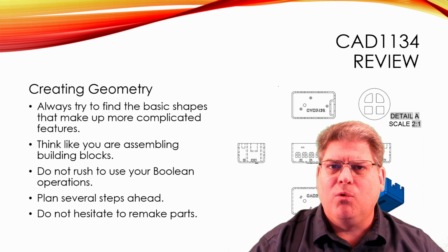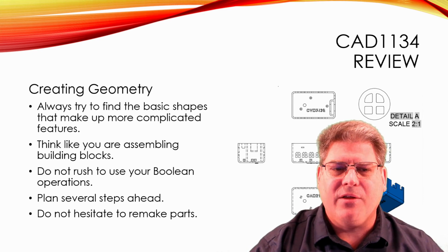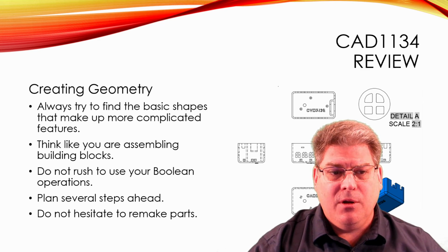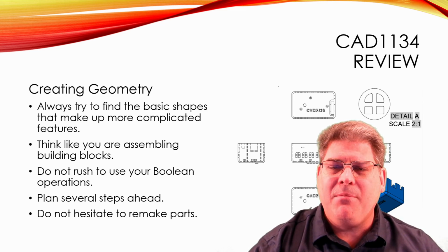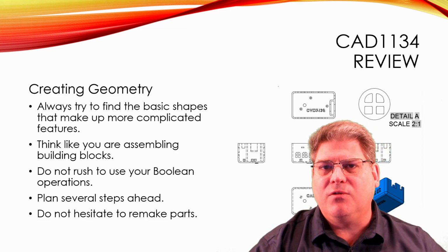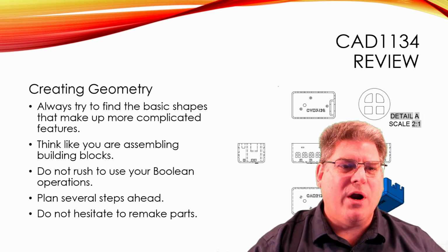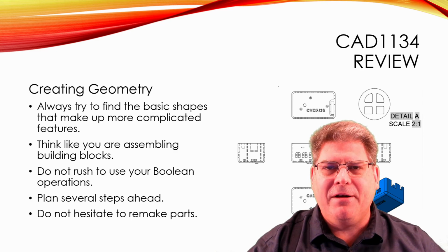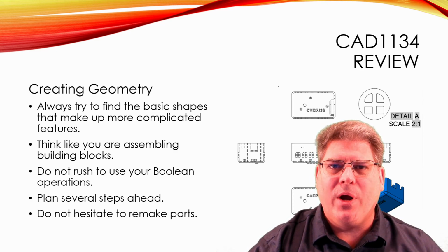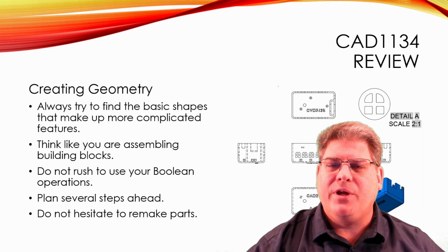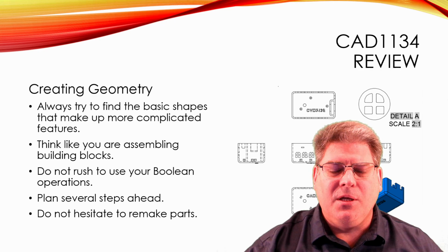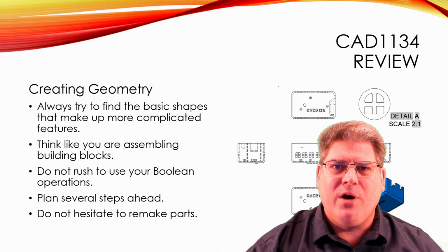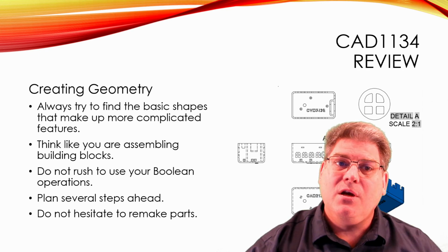You shouldn't, however, rush putting your parts together. For example, the vent holes that I put in here, I changed many times. I didn't know if I wanted 6 or 5 or 4. I didn't know where exactly I wanted them. And so I played around with it until I got it exactly the way I wanted it. And then I used the Boolean operation to do the subtract. The same with the addition of this cord grip that's in here. You want to make sure that it is where you want it before you finally press enter.